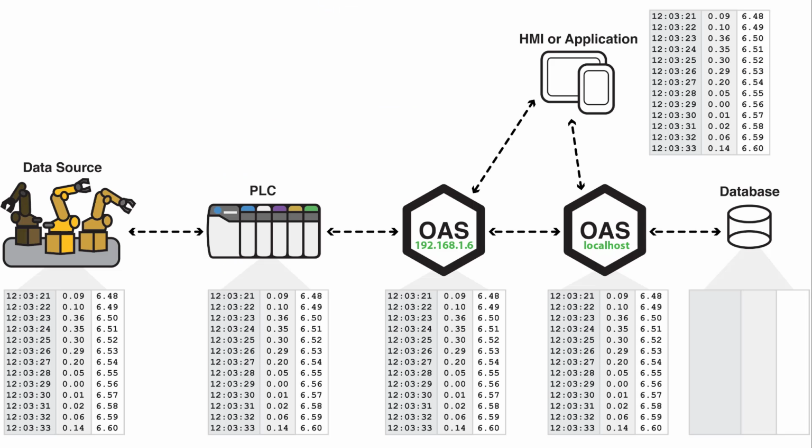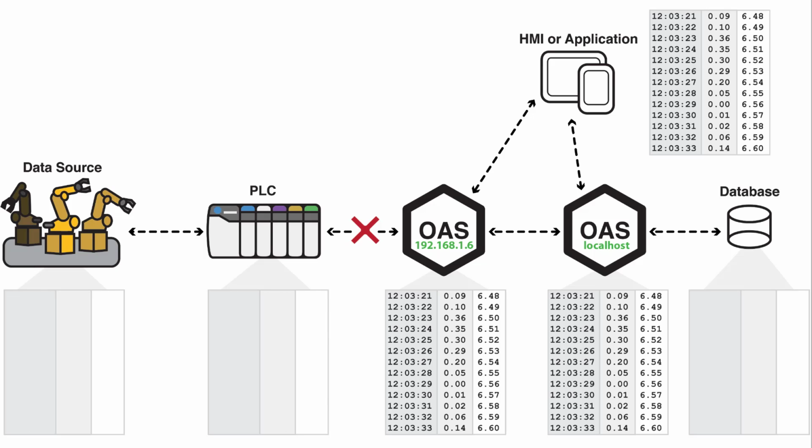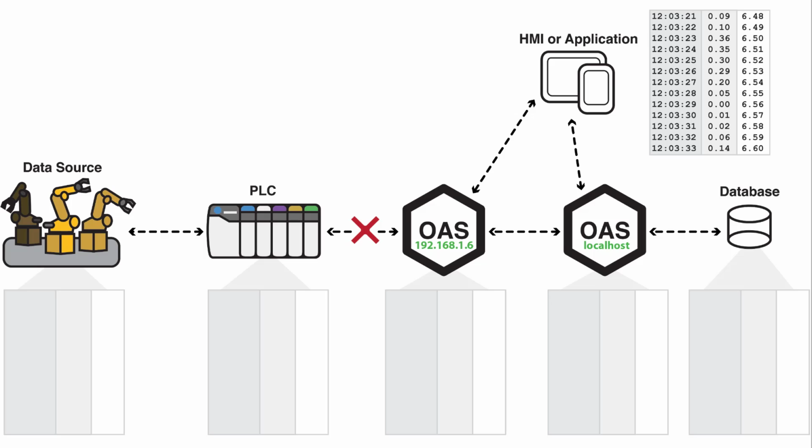Now, what if you have a communication failure back to the data source itself? Remember we talked about obtaining values from the controller in a buffered format, with that article talking about logging buffered data from a controller or a PLC. If you had, say, a controller failure during that downtime, and we're using that technique to log from buffered data, the controller itself would be able to cache and buffer the data locally during that downtime. So that would be easily handled.